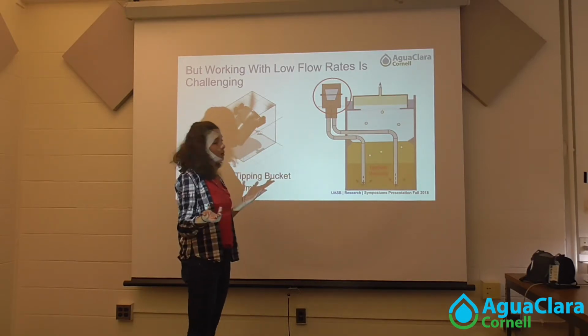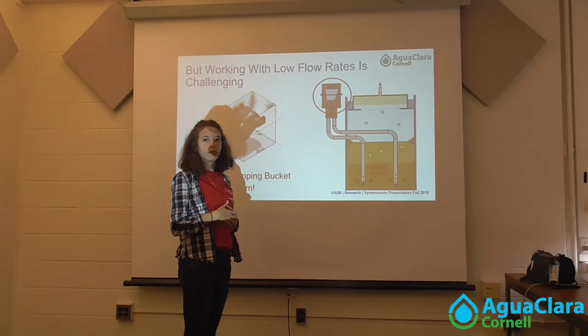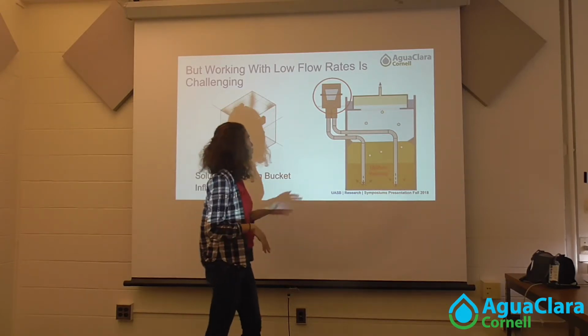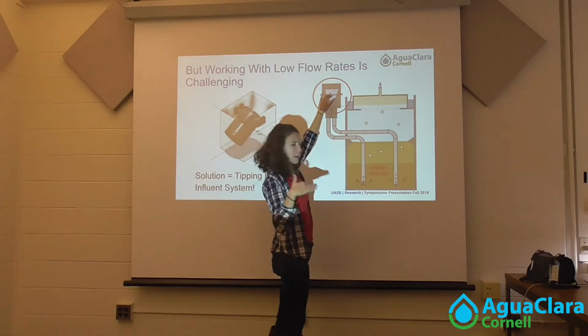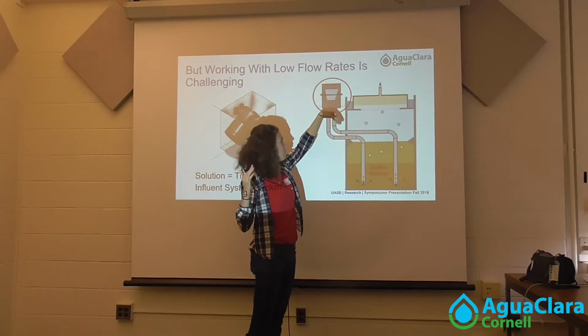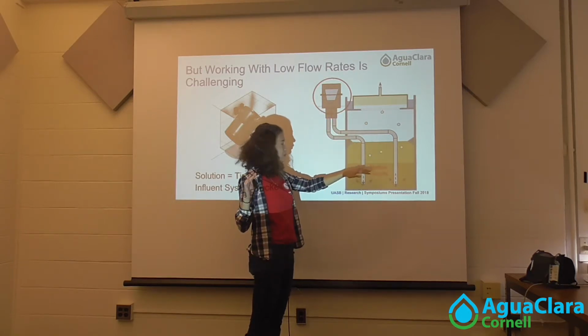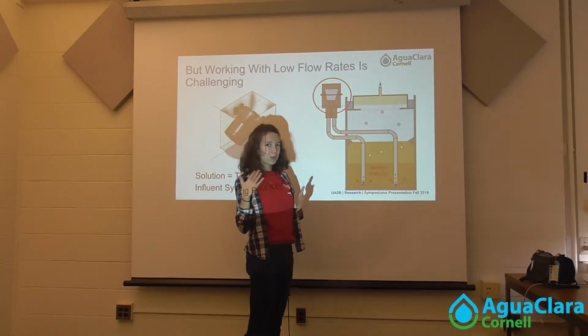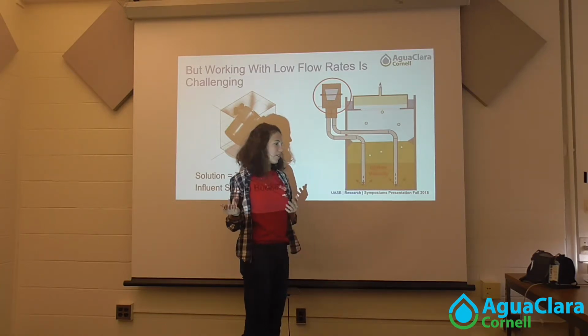So this is where our tipping bucket comes in. Keeping with, like Ian said, an electricity-free system, water will just flow through the tipping bucket until it reaches a certain weight. The bucket will tip over and pour the water down, and that way it creates a nice pulse of water to properly fluidize the bed.